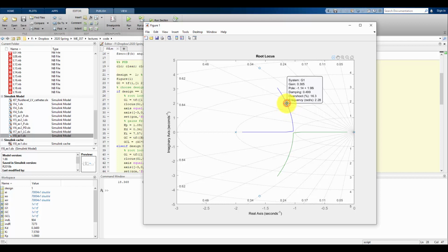So again, I only need to find one of them, so I'll just do the one on this blue line. If I keep increasing the gain here, we can see that the pole is shifting slowly. I'm going to take this just to 2 digits. I see that I can get a pole of -1.15 plus or minus 2.08j if I have a gain of 0.34. I can't really get any closer to the more precise pole at 2.11j.